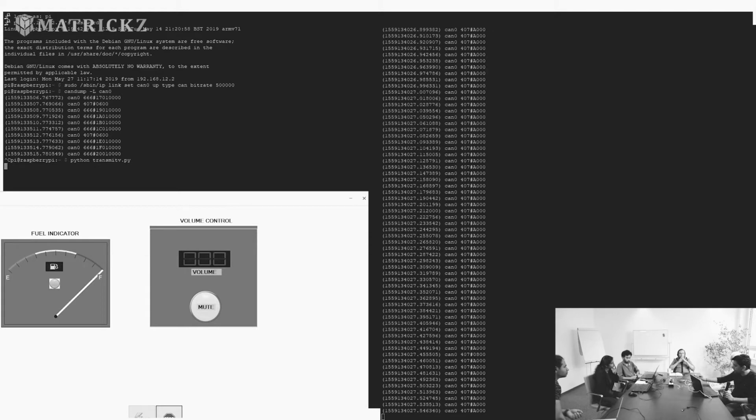So the messages the Raspberry Pi puts on the CAN override the messages that the actual ECU puts, and I can make the other ECU, the simulated cluster, behave exactly as I want. As I told you, this requires an analysis of the messages on the CAN and a bit of reverse engineering.